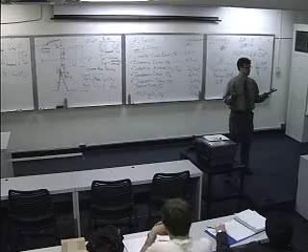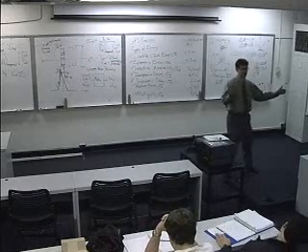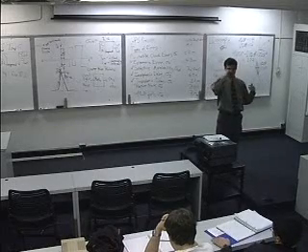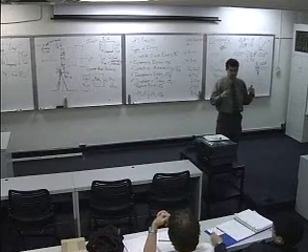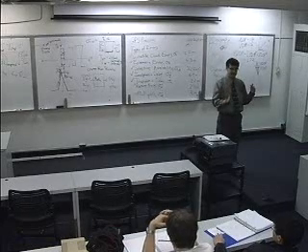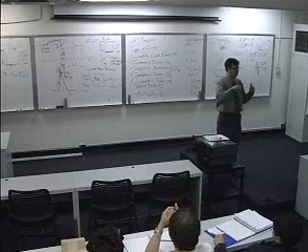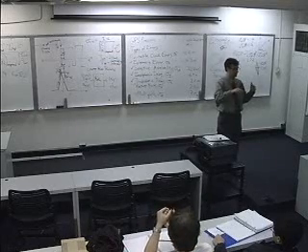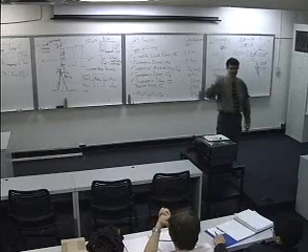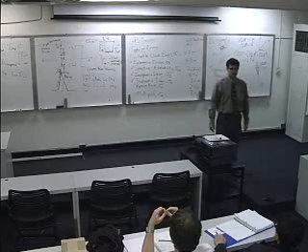You will see, especially in hybrid systems where you might be using time of arrival and signal strength and some array antennas, if you've got that kind of hybrid system, then they may actually take the different types of dilution of precision for each mode of your location and call it one time dilution of precision, and the other one angle dilution of precision, the other one receive signal strength dilution of precision, something like that.